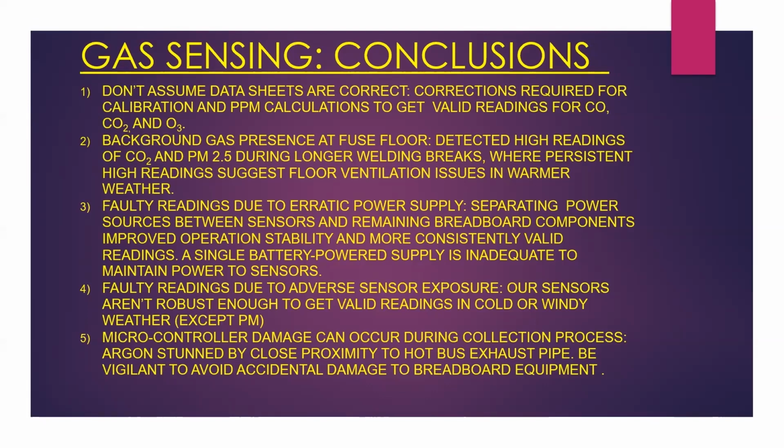Another conclusion is that faulty readings were also due to adverse sensor exposure. Sometimes this was pointed out in the data sheets, and sometimes it wasn't. Our sensors basically were not really robust enough to get valid readings in inclement weather, where it was too cold or too windy, with the possible exception of the particulate matter sensor, which works completely differently than the other 3 electrochemical sensors.